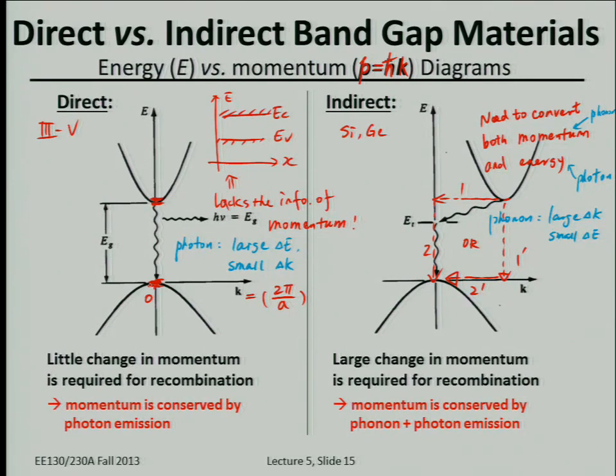So it's more likely that an electron first gets trapped by a defect or an impurity atom like gold, and then later the hole comes along and gets trapped at the same site. So that's how recombination generally occurs when you have an indirect band gap. Indirect just means that the minimum electron energy and the minimum hole energy are not really at the same momentum.